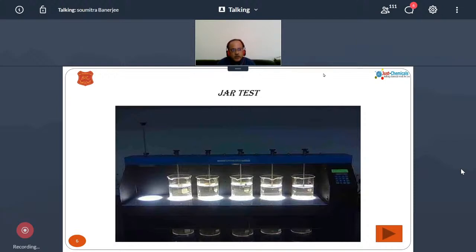Whereas the iron also goes into the reverse osmosis membranes and can foul them, and it can also go and settle down in the cooling water system somewhere and can cause microbiologically induced corrosion, as under the deposit of iron there will be a lot of anaerobic condition, and a bacteria called desulfovibrio gets generated over there.